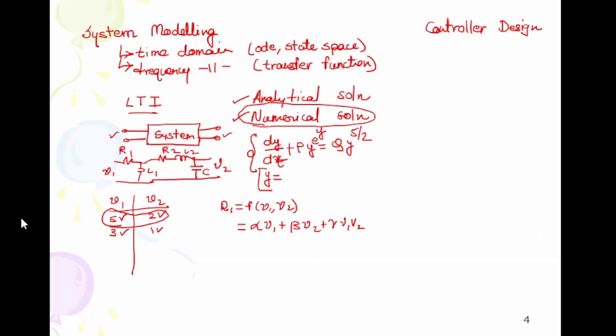Now, instead of a complex circuit like this, suppose I have a simple RC circuit. Same problem, right? The values of R and C are not known to us, but the input-output data is available to us. Now, for this particular circuit, we know what V2, the voltage across the capacitor, will be. You have a switch which is closed at time t equal to 0. So what will be VC or V2? It will be V1 times (1 minus e to the power of minus t by RC), right? Suppose we are conducting an experiment, we apply an input. So this is the waveform that we will get in our oscilloscope as the output. And what is your job? Your job is to find out the value of R and C.